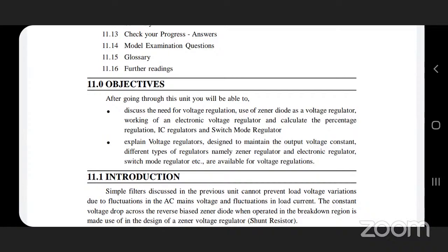That is enhanced by going from a single diode rectifier to a two diode rectifier. Before discussing all these things, you have to know what a PN junction diode is. In forward bias, the diode conducts current; when the voltage increases, the current also increases. In reverse bias, when the voltage increases, the current is not conducted.